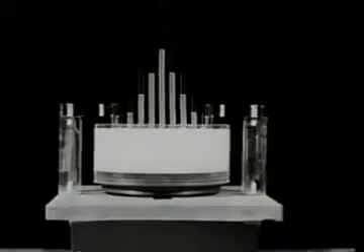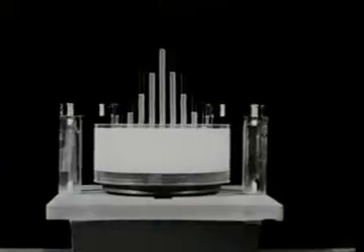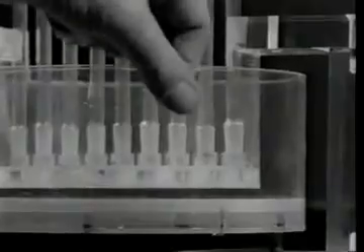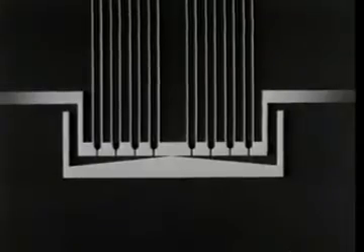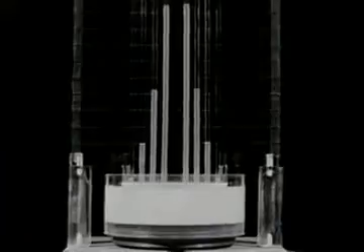Indeed, quite high stresses can occur near the center, and this principle has been used in the design of a pump for molten plastics. If the bottom disc is replaced by a very shallow cone, the stress normal to the stationary disc varies linearly with the logarithm of the distance from the axis of rotation. This logarithmic relation is expected for all memory fluids.